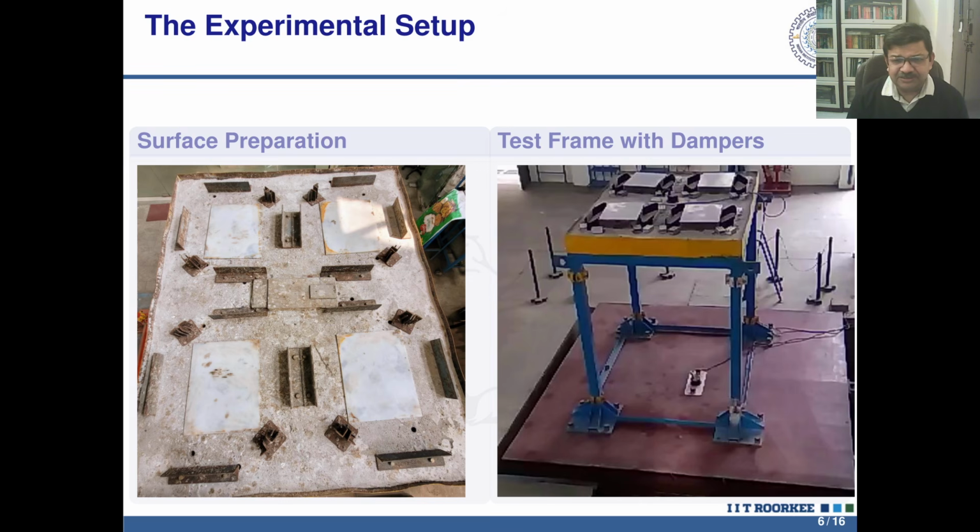Sheet metal of required thickness and tongue of required length, and we can fabricate these leaf springs and then give heat treatment at site, and they are ready to be used as spring material, and very effective. You don't really need any specific helical spring of specific stiffness, depending on whatever natural frequency is to be targeted. We can fabricate these leaf springs accordingly of desired stiffness, and they can be inserted.